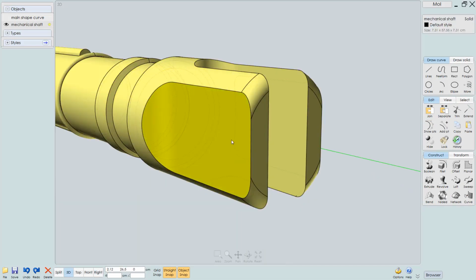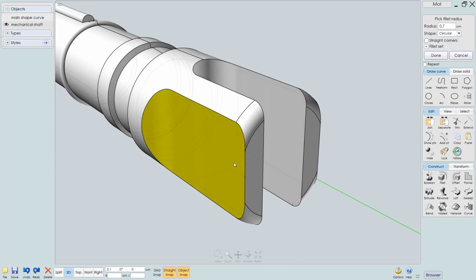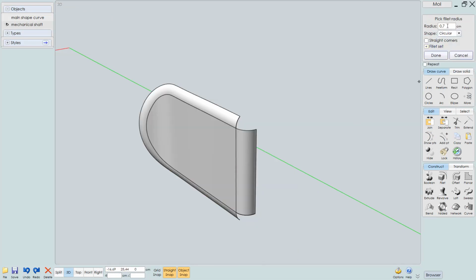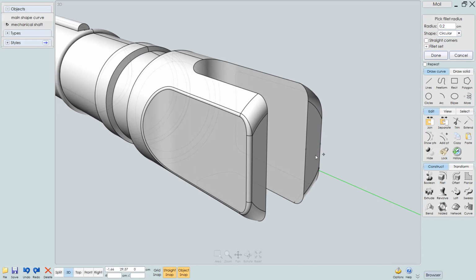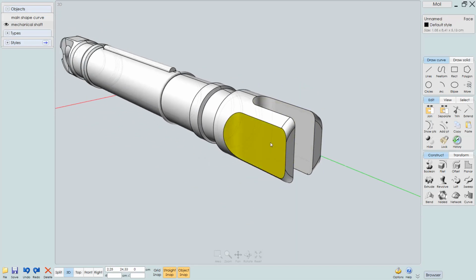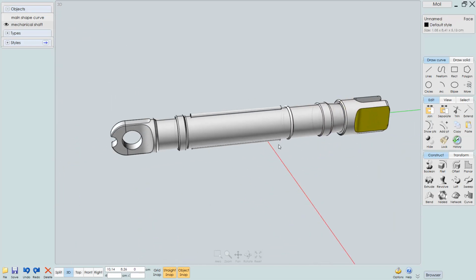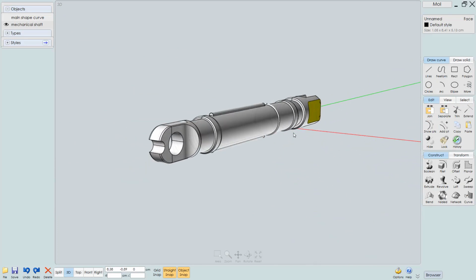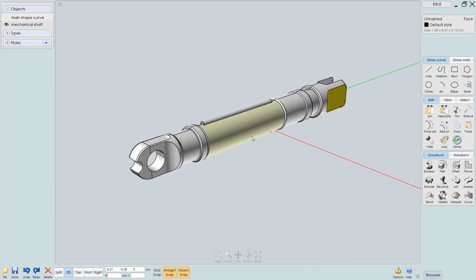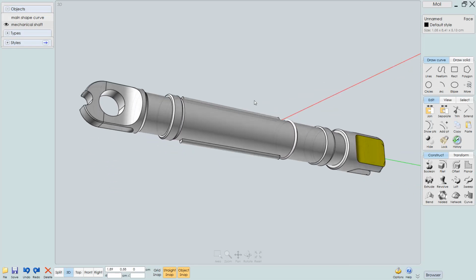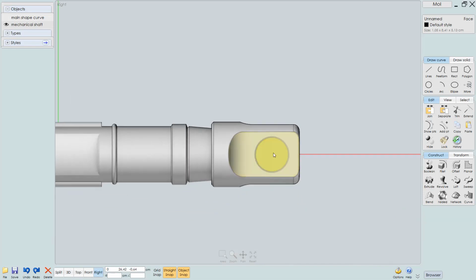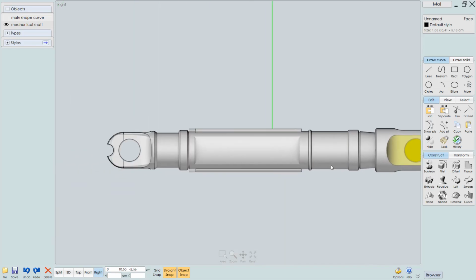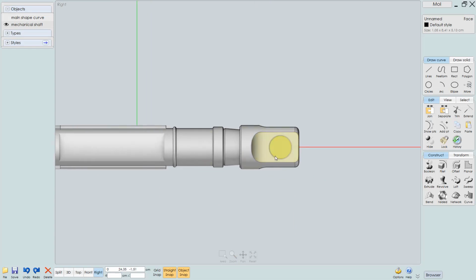And I'll just select this face here and try a fillet. And it's a bit big, but basically it seems to work. So that's good. So no problems here. We can fillet these edges. And actually filleting is just what we can do right away, because I think we've added all the details except for this hole. We need to get that in there. But other than that, we're pretty much done with this object.